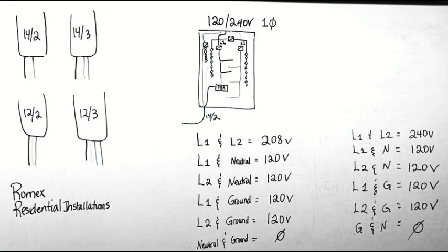So this is a much more effective way to wire a circuit, in parallel, and 99% of homes are wired in parallel. We give multiple paths for current to go back to the power source so that our loads are not dependent on each other. So what do we do when we have a parallel circuit? We're giving multiple paths for current to go back, do the work that it needs to do. For example, turn on this load, turn on all 10 loads, and then go back to the power source, right?